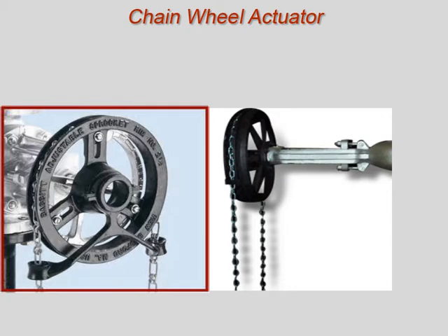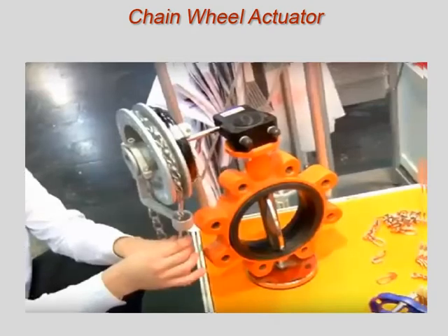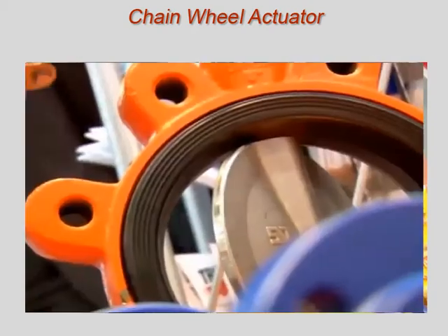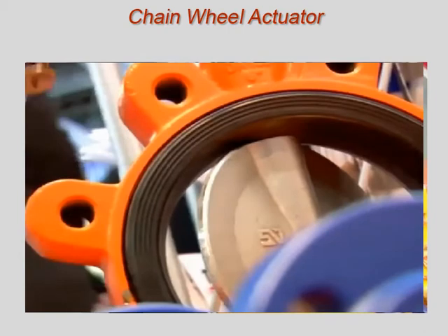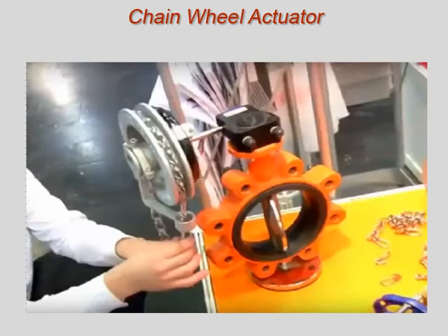If the valve is inaccessible during normal operations due to being in the overhead, or is so big that a standard hand wheel will not provide sufficient leverage, a chain wheel actuator may be installed. Typically, this actuator is used when the valves are above reachable level and scaffolding or platforms are not available to operate the valve safely. When operating any manual valve, wear gloves, not like this guy. It is especially important when operating chain wheel actuators. The chains are sized to make it easily accessible and operable from normal levels. Just like other manually operated valves, the failure mode is as is, used in accessible areas, and righty-tighty.